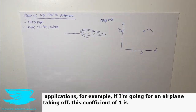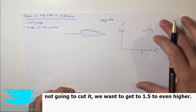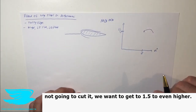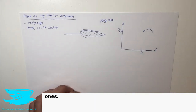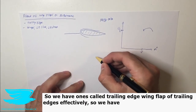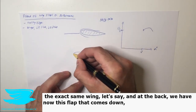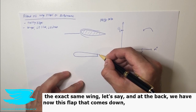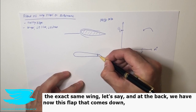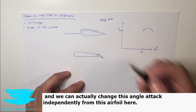For example, if we have an airplane taking off, a lift coefficient of 1 is not going to cut it. We want to get to 1.5, 2, even higher. So to do that, we have these things called wing flaps, and we have a bunch of different ones. So we have ones called trailing edge wing flaps, or trailing edges effectively. So we have the exact same wing, let's say, and at the back, we have now this flap that comes down. And we can actually change this angle of attack independently from this airfoil here.